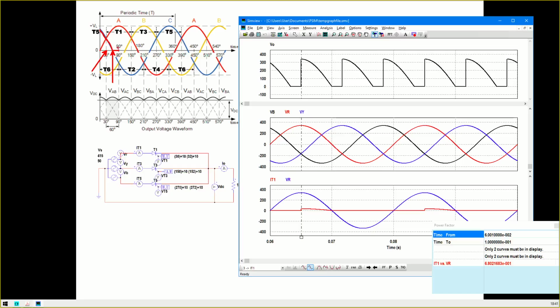So beyond 30°, for example, in this case we have 60°, and after we trigger thyristor 1 at 60°, then we'll see the output voltage waveform again, and that follows thyristor 1 or the phase voltage until it reaches that point. Then it goes further and does that.